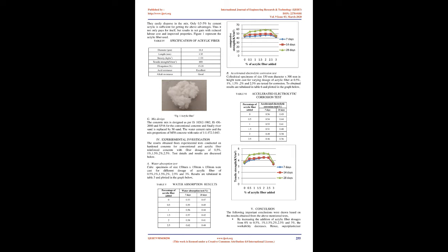E. Superplasticizer. In order to improve the workability of high-performance concrete, superplasticizer in the form of polycarboxylic ether-based superplasticizer, Glenium 8233, was used as a chemical admixture. The product has a specific gravity of 1.09 and solid content not less than 30% by weight of cementitious material.